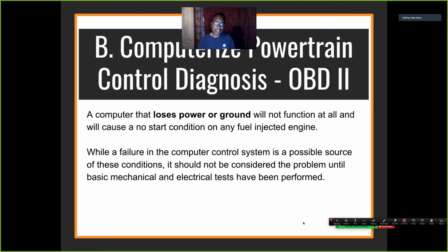They say no sensor has 5 volts to it. Could be a shorted sensor. If I don't have an injector trigger, fuel, or spark, that could be an input problem causing no RPM signal.